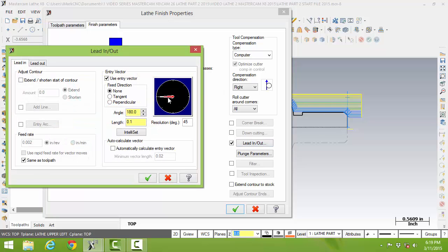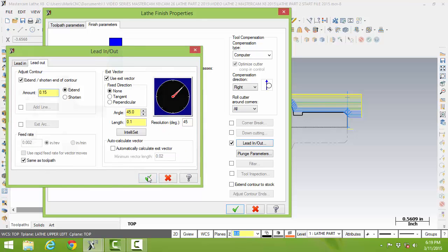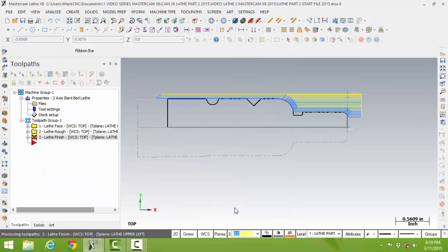We're going to come horizontal in. If we're going to add an extension to that, let's just say 50 thou. A lot to me, but that's okay. The lead out, we do want to lead out, and I'll explain why this is important. Because when we do the parting tool, all this material we want to rough off. So when we start the parting tool, we're starting not with a kind of a dip in our part, but a clean cut. And again, we go away from the part. Again, lead in at 50 thou, horizontally in, and arrow pointing away for roughing. We're going to choose OK, and it's going to do the toolpath.